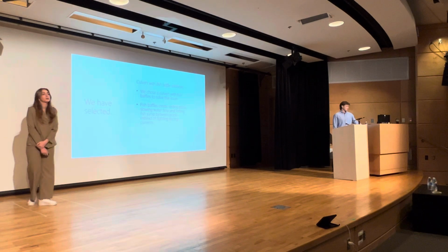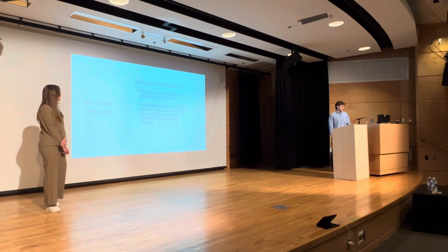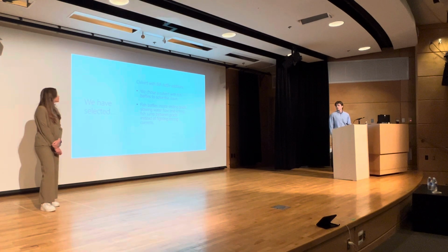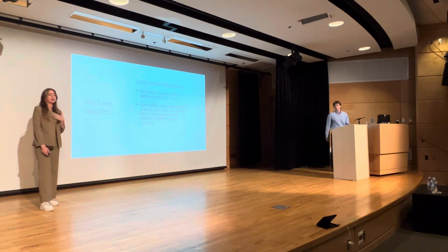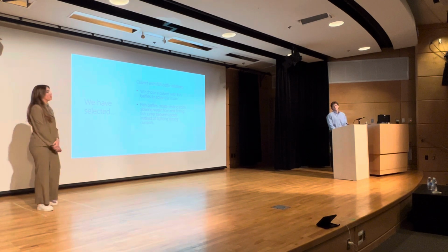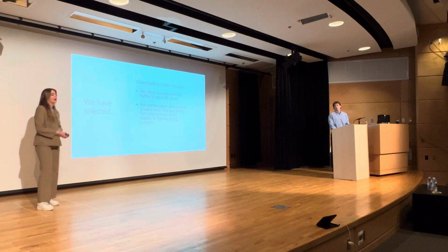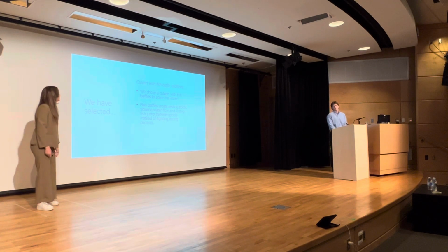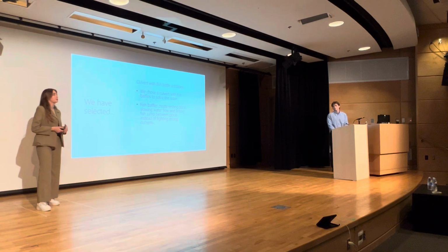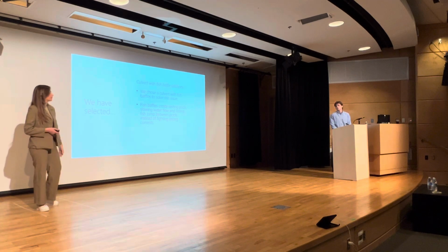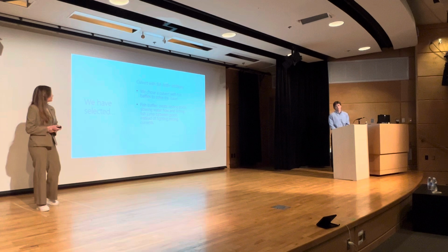So we have selected a culvert with fish baffle additions for this project. This is because our site slope was higher than 5%, and to choose any of the other options except for the embedded, so the open bottom culvert, we needed something less than 5%. Meanwhile, with the embedded, again, the slope is too high, so the flow velocities can also be very high, and we don't want the fill to transport. Fish baffles, as we said earlier, create resting pools so that fish can rest before going through their migration paths, which restores their natural migration paths.